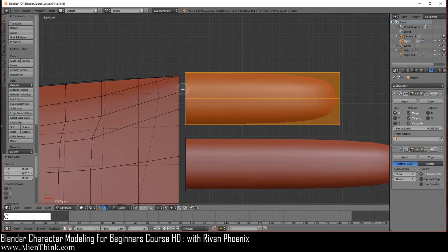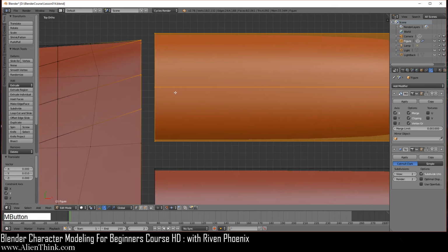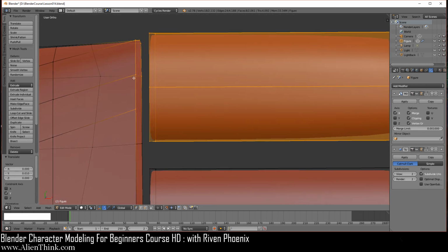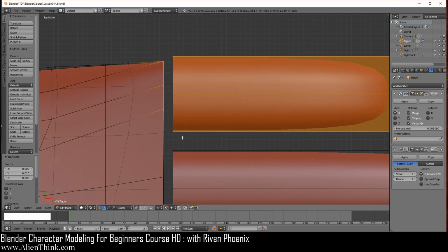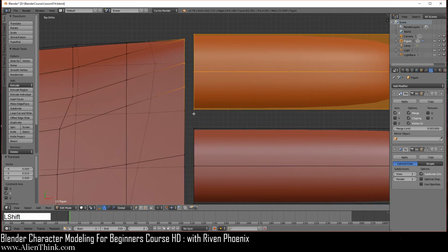Just zoom in, press the C key, and you're going to select all these 3 vertices. I'm just going to show you, if I use the middle mouse button to rotate, this is what I'm selecting. Okay, go back to your top view. Now we're going to come over here, hold the shift key and right click to deselect, and then select it back. You note that because the 3D manipulator jumped over here, you have actually reselected that vertex.